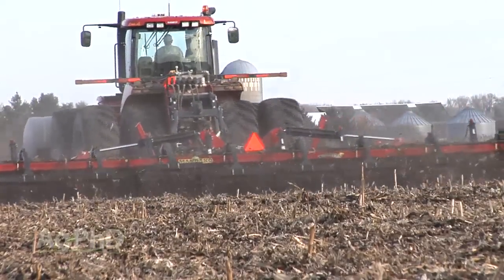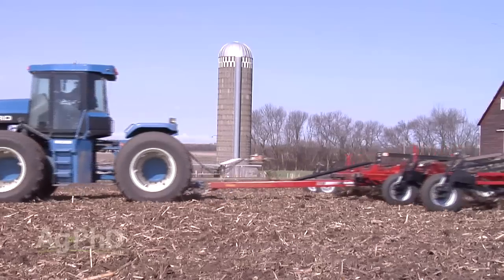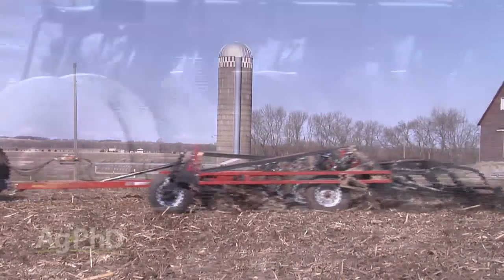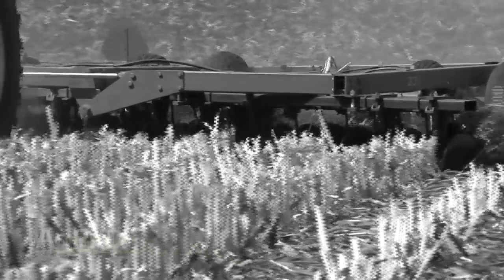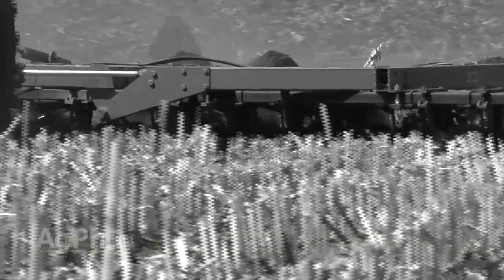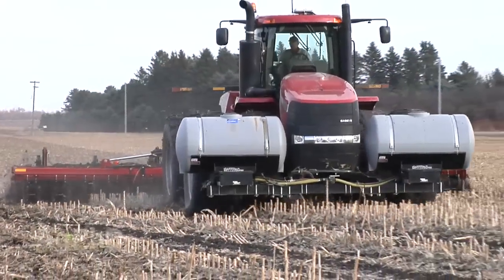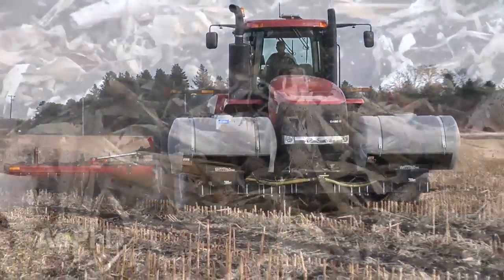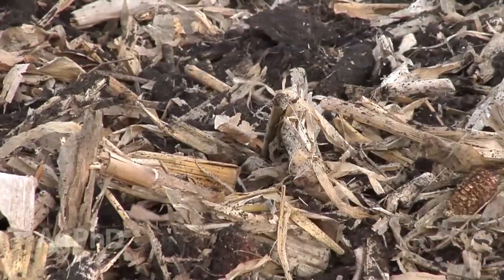Yeah, we've used a twister as well. We've used a number of these different tools, and the point is we're doing vertical tillage here. We don't want to use a disc. That's what we used to do in the old days, but our dad would always say, well, boys, don't ever disc in the spring because you're just going to make a mess. You're going to create a lot of compaction out there. We don't want to do that. With these coulters, you can slice without creating all that compaction. So that's the reason these machines have gotten so popular in the last few years.